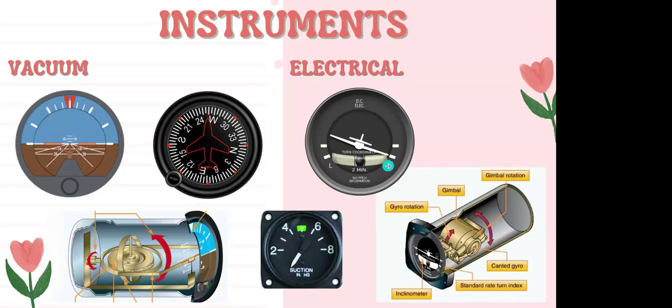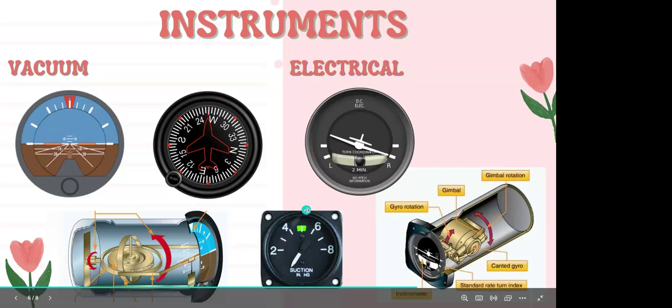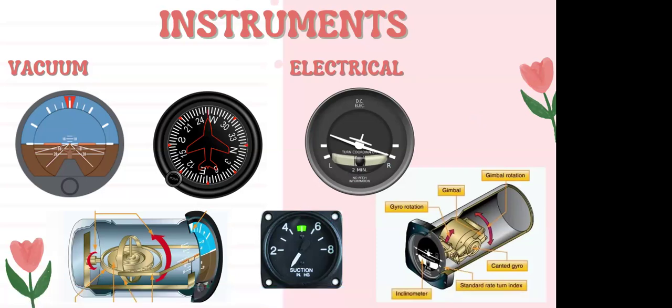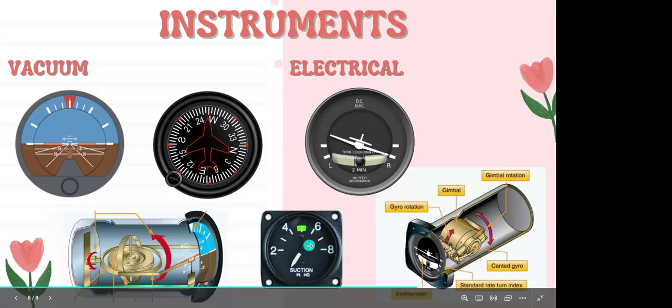Okay. So with the electrical system, oh, actually, one last thing here is with the suction gauge. When you're doing your run up and you go to 17, 1800 RPMs, which depends on the plane that you're flying, and you are doing your magnetos check or you're pulling to idle, another thing you're looking at is your suction pump or your suction gauge.